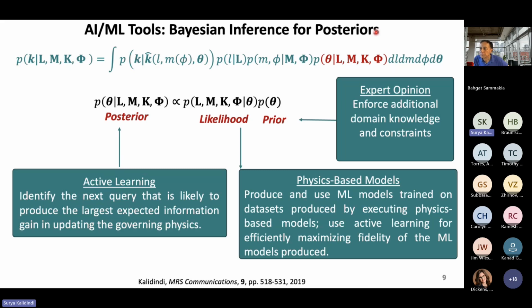You define an objective function and you minimize the difference between the experimental observation and the simulations. Oftentimes there are identifiability issues, in the sense that if the number of parameters is large, the matching solution, the calibration, is not unique. There are multiple combinations that might fit the same experiments.